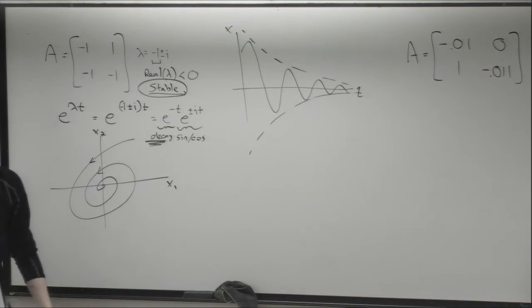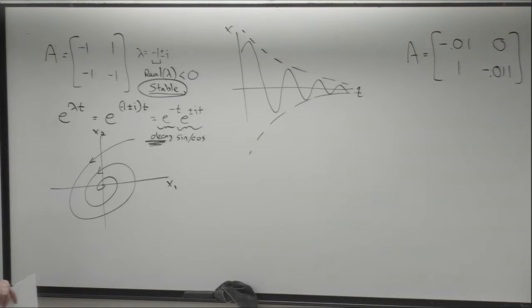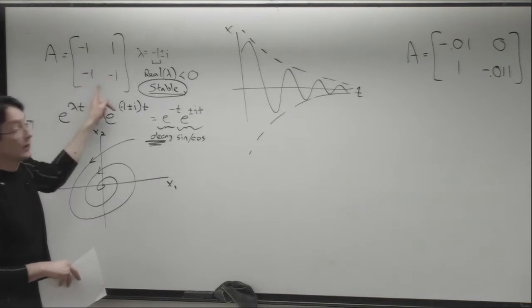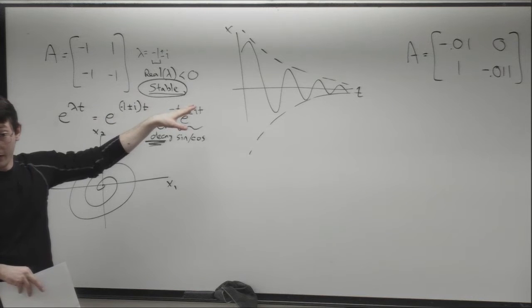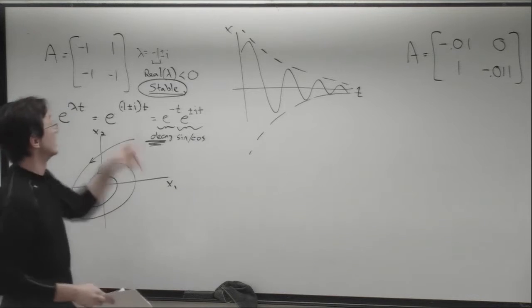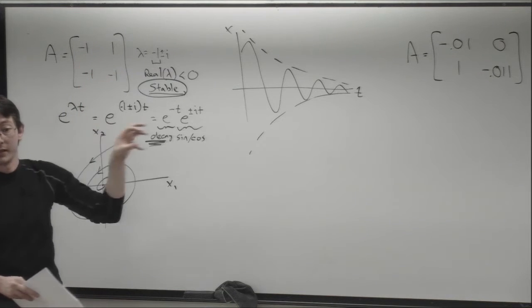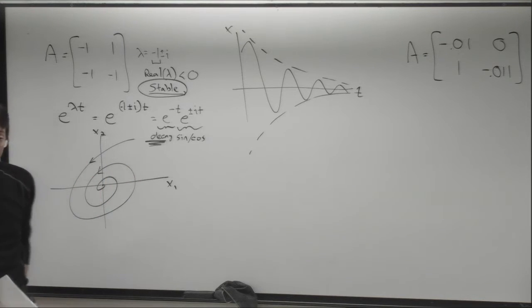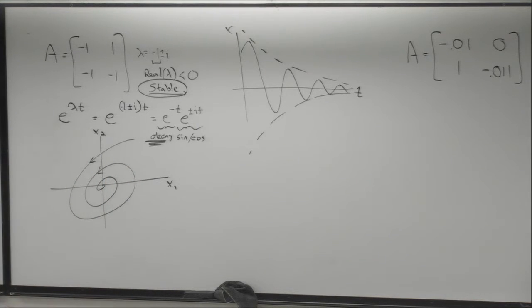So is there a physical coordinate to the oscillatory terms that we should think about? So when we dealt with the spring mass system, we had a slightly different form of the equations, but we also got purely complex eigenvalues. So what I would recommend doing is take that spring mass system and add a damping term and see how it changes the A matrix. And you'll really see which terms contribute to damping and which terms contribute to pure oscillation. But the oscillatory term really corresponds to the position and the velocity being out of phase with each other. Okay, good.